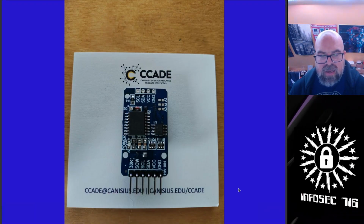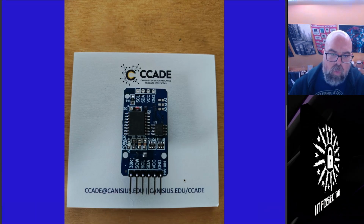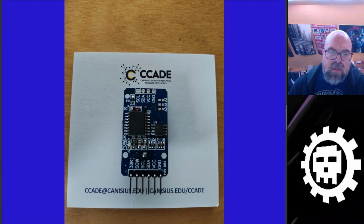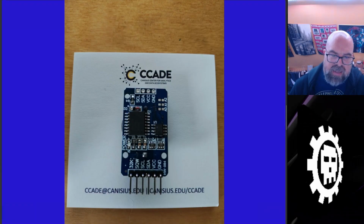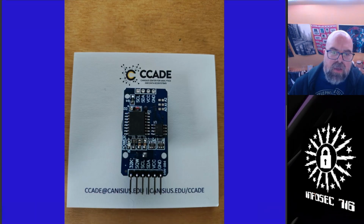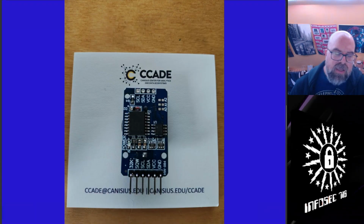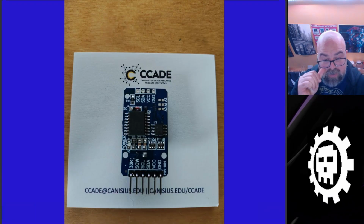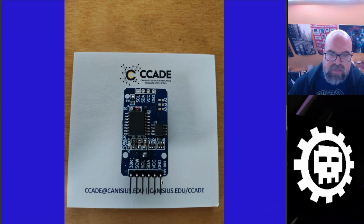This is an RTC module. Let me just point out a few features here. One, we have these 6 pins along the bottom. So these 4 are the ones that we're going to use. This is our serial clock, our serial data, our voltage in, and our ground pin. Over here, we have a wave generator and a clock signal. Those are used in some hardware designs, but not in anything that we're doing today with the Arduino. So we can ignore those 2 pins. We're only concentrating on these 4.